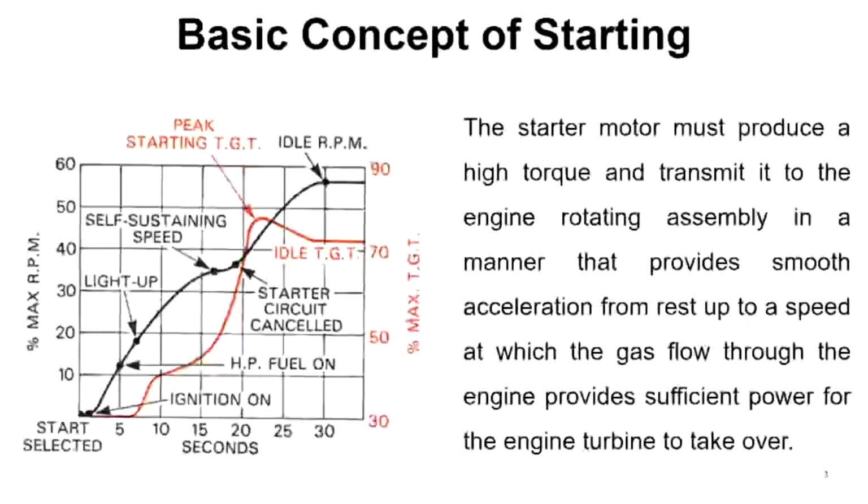So first of all, the basic concept of starting. Basically, the starter motor must produce a high torque and transmit it to the engine rotating assembly in a manner that provides smooth acceleration from rest up to a speed at which the gas flow through the engine provides sufficient power for the engine turbine to take over.